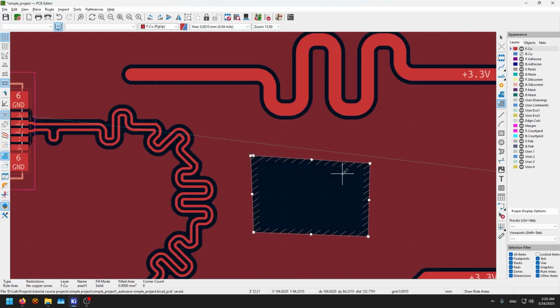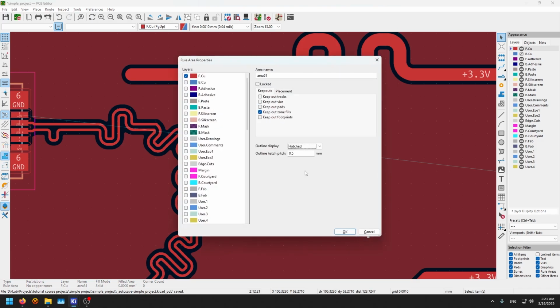Press B again, and now this area is assigned as an exception. This is important if you want your inductor, for example, to have the copper ground, which is for the layer 1, not really poured under it, which is recommended, but you still want other layers to be okay. You can do it from here.